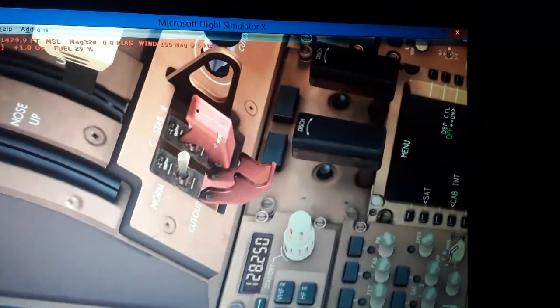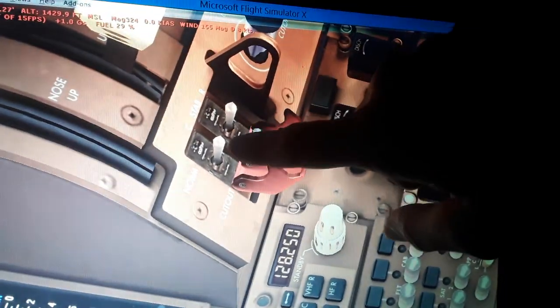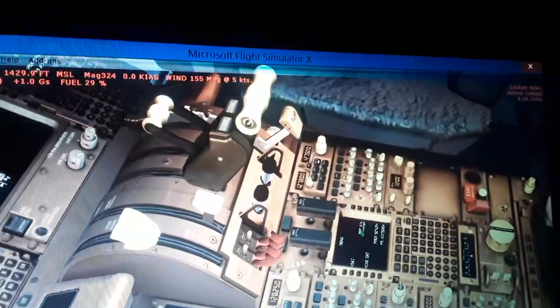So I told you we have the fuel flow to the engine, we have the fire extinguisher, and this is the horizontal tail trim, the speed brakes, and the horizontal tail trim stabilizer. We have a failure of the hydraulic fluid system. We can disconnect from the normal to the cutout the system, the auto trim function from the horizontal tail trim stabilizer.